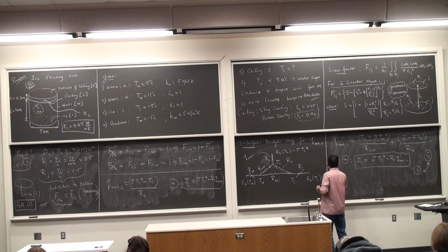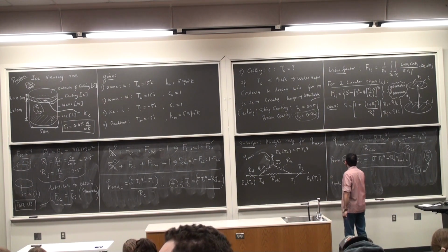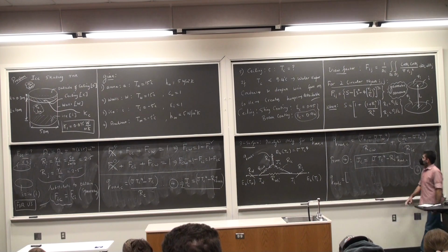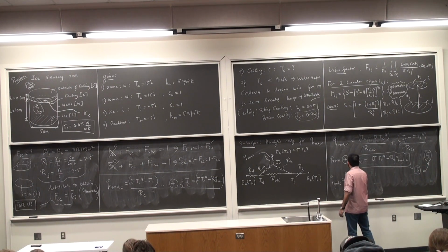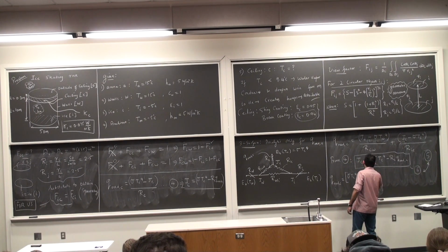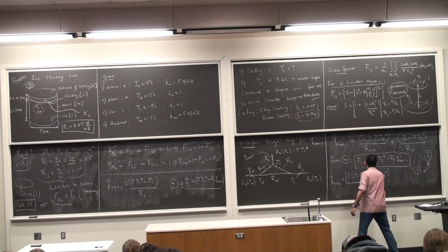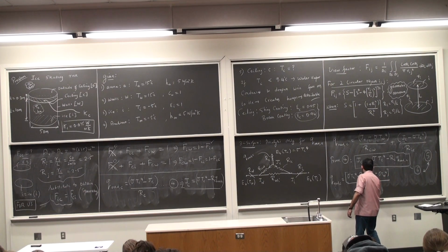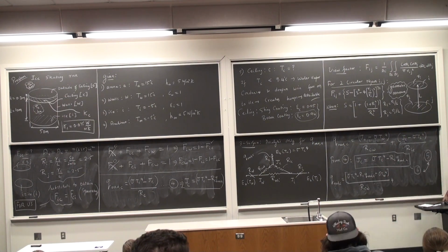So Q radiation C is, instead of Jc, I have all of this. Sigma Tc to the power 4 minus Rc Q radiation C minus sigma T wall to the power 4 by RCW plus, bear with me, I'm going to substitute one more time for Jc.